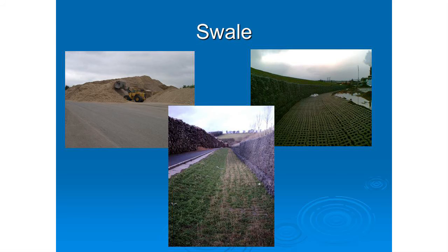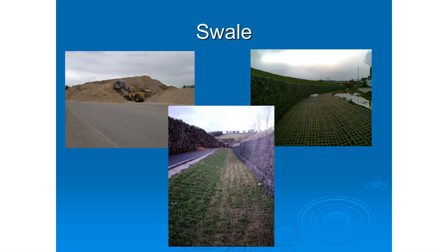And that wetland has been designed with gabion walls in there with limestone in it because there's a pH buffer to act as a pH buffer in there as well as removing formaldehyde. So these are just pictures of the kind of silt load that we've got to deal with on the right hand side. That's a swale. We've put armouring in there because they're going to have to clean out the sawdust very, very frequently. And in discussions with the client, they wanted that in there. I'm not sure now whether I would actually put that in these days, but it was a design decision at the time. And then once it's growing, that's what it looks like at the bottom once it's growing up.